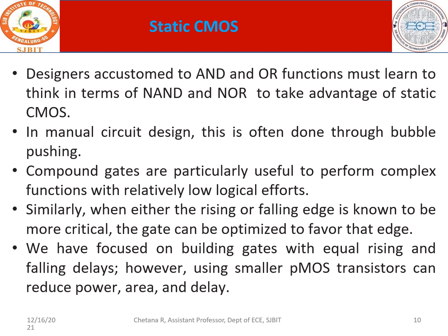Now we still focus on static CMOS. So all the while designers are accustomed to AND and OR functions, and now they should think in terms of NAND and NOR. So in manual circuit design this is possible, and it is done through bubble pushing. So what exactly bubble pushing is we will see in the forthcoming slides. And we also have compound gates. These compound gates are particularly useful to perform complex functions with relatively low logical effort. So along with this we also have to understand what a compound gate is.